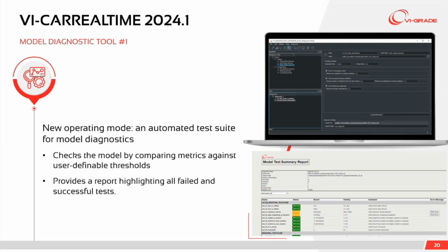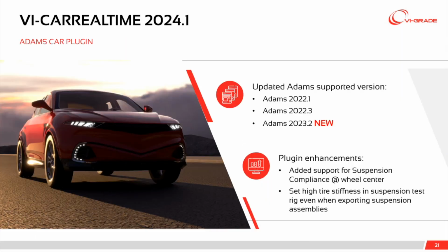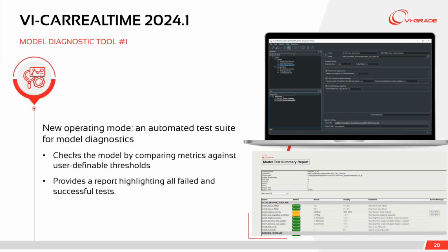Last, let me also speak a bit about the diagnostic tool, which has already been mentioned by Jody before. The diagnostic mode is a completely new operating mode in VI-CarRealTime that basically allows to define easy to run test suites in which after each simulation, the software automatically performs tests of user-defined metrics against a number of user-defined thresholds.